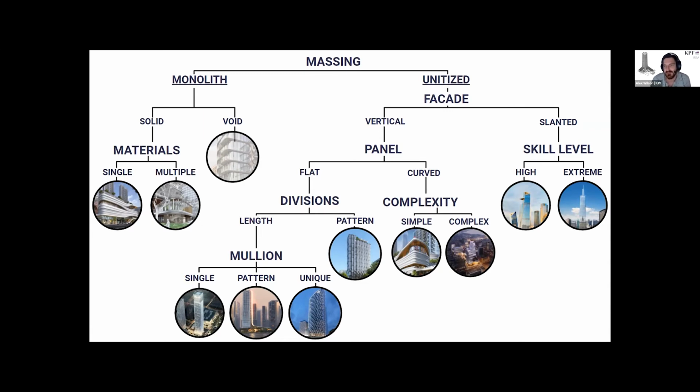If you were taking a doubly curved wall with voids out of Rhino, you're not going to have all those advantages of using detail levels, things like that. So if you do have a complicated repeating void situation, maybe look at using Rhino.Inside to create your voids, optimizing the points so it's not too heavy, bringing those voids into Revit itself, and then cutting just a sister wall.